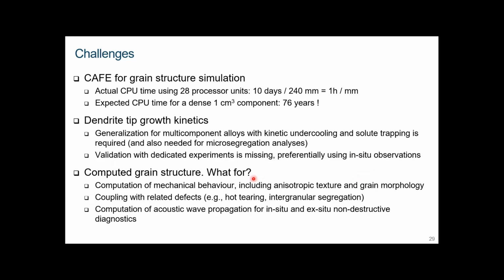What is this computed structure for? I've shown you an example of using this grain structure to compute mechanical behavior. Actually, there are other reasons why we want to have solid mechanics coupled during the formation of the structure. This is to model hot tearing and intergranular segregation. And we are starting another project on welding, to also use this grain structure to compute acoustic wave propagation for in situ non-destructive diagnostics.